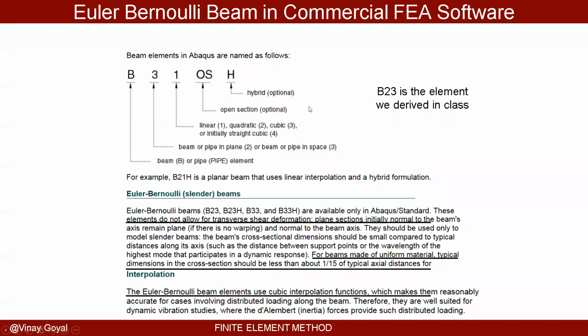So the beam elements are approximating the behavior. It's not a perfect solution, but there will be some axial deflection associated with the beam deflection themselves. What this is covering for is additional axial load that comes from applying an axial load.